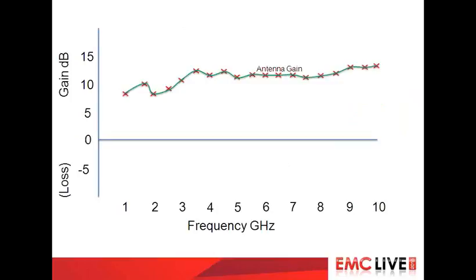And so I took that from the plot you saw earlier, where I put the yellow lines, intersecting lines to identify, and then I put all the crosses for similar intersections, and I joined them together, and there is your antenna gain, all the way from 1 to 10 gigahertz, the system we're designing. And there is your cable loss. Now, I have loss in brackets on the left-hand side there because technically, minus 1 dB of gain is, of course, 1 dB of loss.